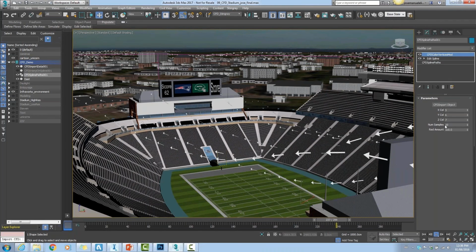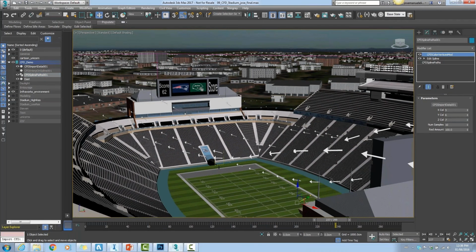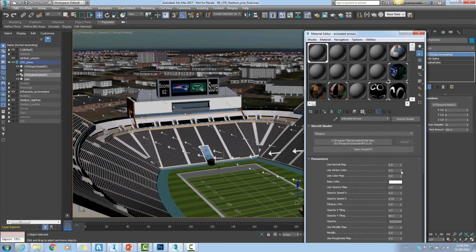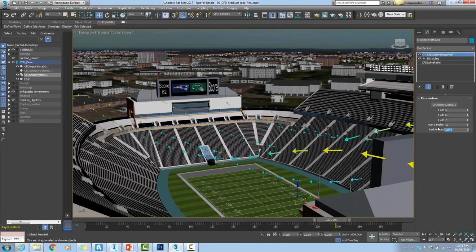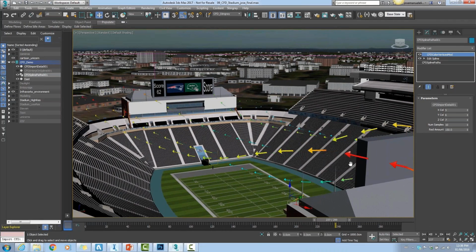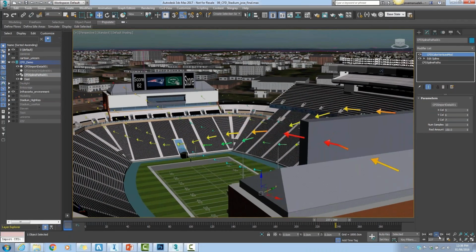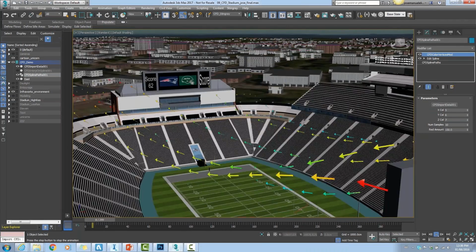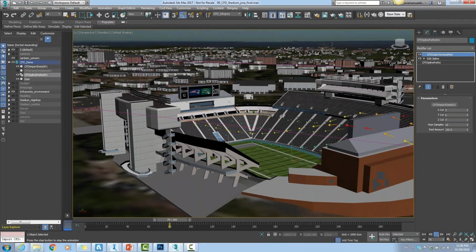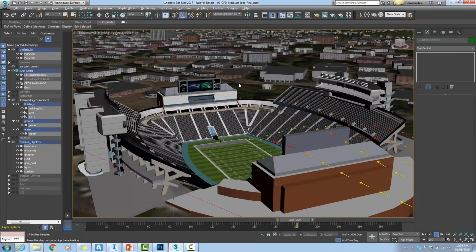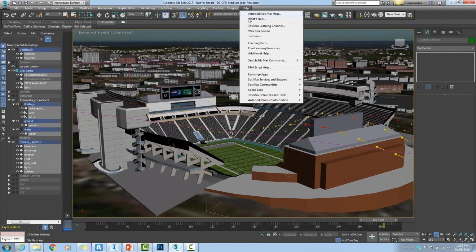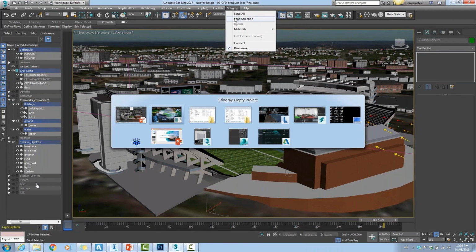We're going to apply this CFD color vertex modifier to our splines. We're going to link it to the imported data, and we're going to visualize this using vertex colors in the viewport. And this is something that Stingray will also be able to do. Whatever is more red is wind moving faster. Whatever is more blue is wind moving more slowly. All right, so it's pretty straightforward and easy to understand what's going on here. And because this is all just polygons and textures, all of this is ready to go into Stingray with just a couple of clicks.